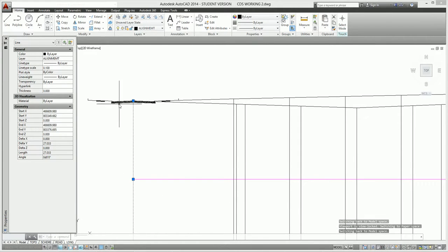In terms of the area inside the typical cross section, I've given the typical cross section priority. The heights as determined by the typical cross-section take priority over the contours because they are more accurate. So there was a 27.2 contour right in here just on the boundary, but I've taken the boundary value as given by the typical cross-section.